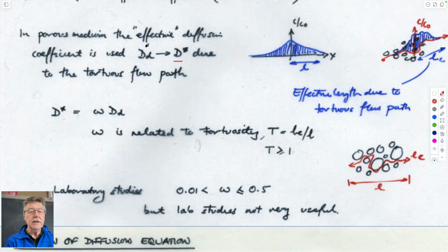And so you can imagine that if you take this term out of your reference book in the library for whatever stuff is diffusing in water or whatever other solvent it is, you have to modify it in some way. And you can modify it by multiplying it by a coefficient that relates to tortuosity. And you'd expect that this tortuosity would somehow be proportional to the length traveled versus the actual as the crow flies length.